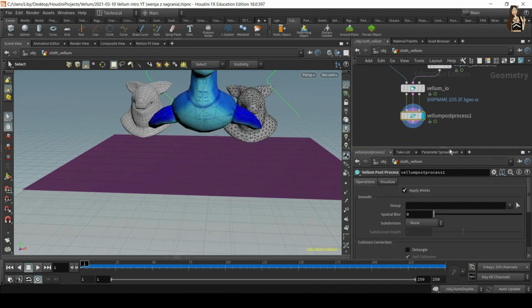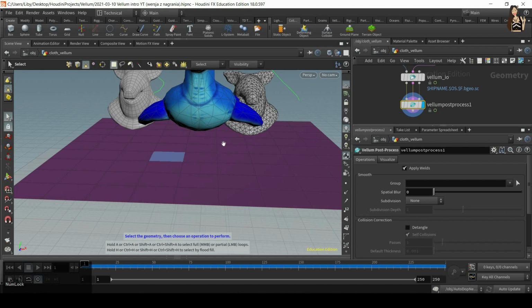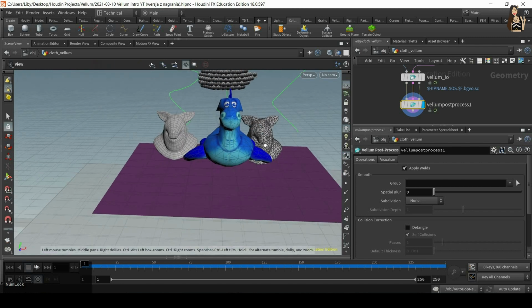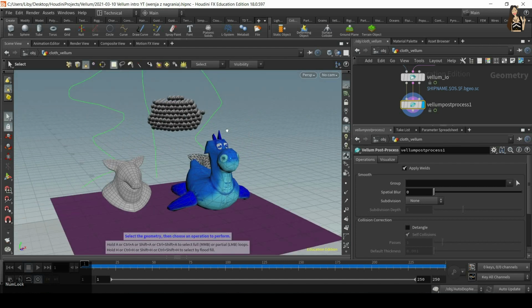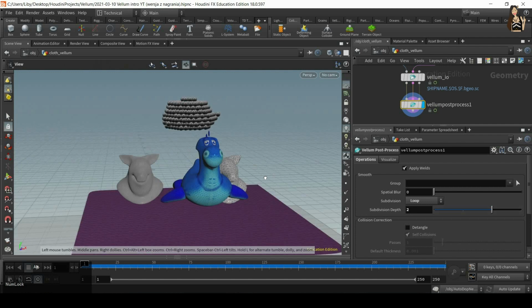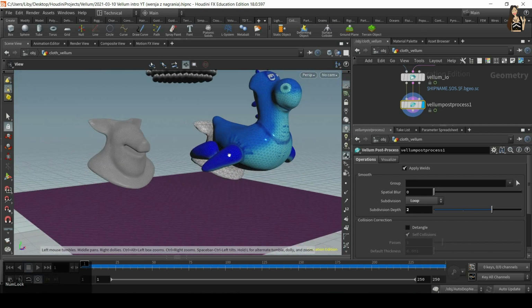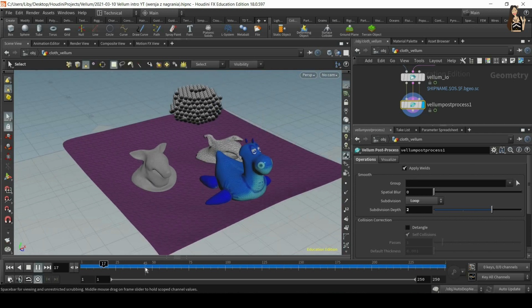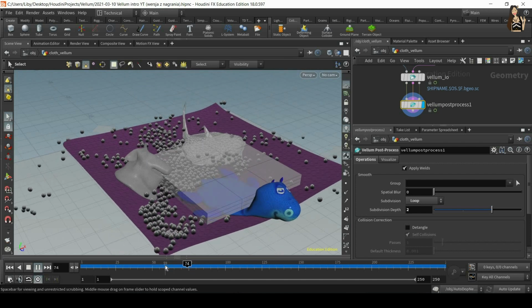As I mentioned at the beginning of the video, post-processing allows us to, for example, subdivide the geometries. So we can subdivide the cloth, we can subdivide the balloon and the Softbodies. However, there are objects that cannot be subdivided, such as the wires or the grains. So let's see what happens when we use the subdivision. Let's change the subdivision type to Loop or Catmull-Clark. These are our two options here. And if I increase the number, you can see that these geometries are much smoother. And when I play the cache, we'll also get a nicer outcome. However, the hair is gone.